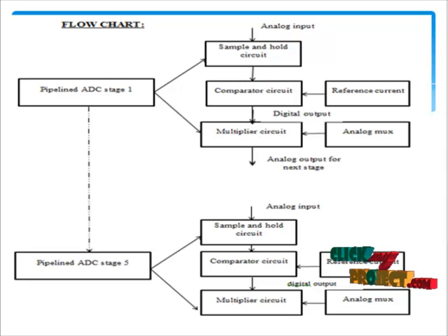The analog-to-digital converter uses a sample-and-hold amplifier to take the input analog signals. Even though increasing the input frequency may increase the power and noise of the ADC, a SHA-less architecture has difficulty achieving high SFDR for IF sampling applications with fast, challenging input signals.